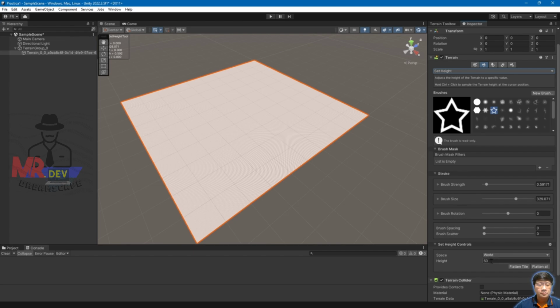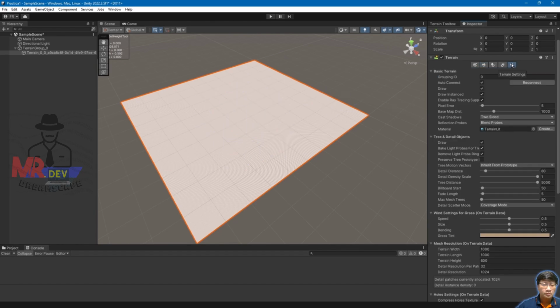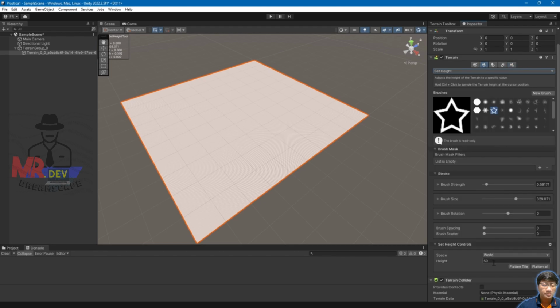Here we have the height, the maximum height we want to reach. Remember that the maximum height of the ground is 600. By default, if we go here to the properties of the land, at the bottom we see 600. But of those 600, I can put 20, 53, depending on what we want, the maximum height we want to reach.